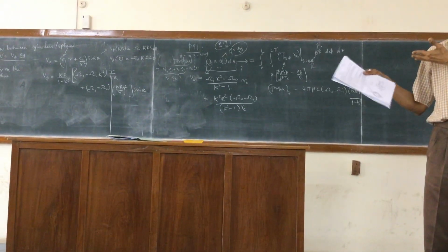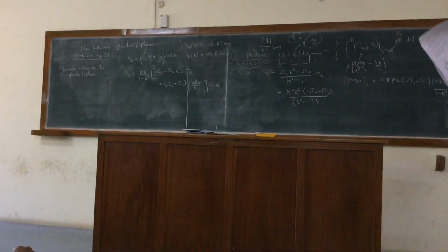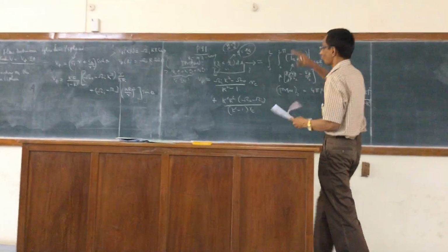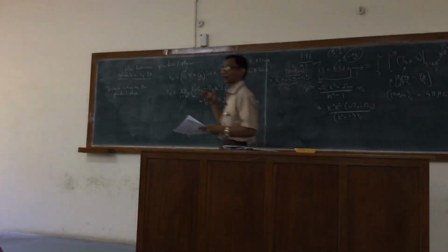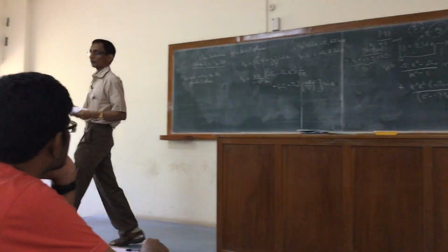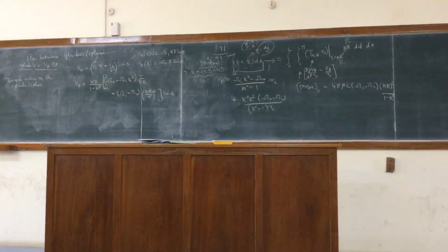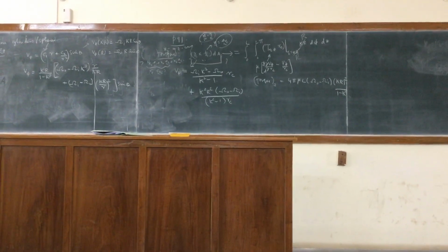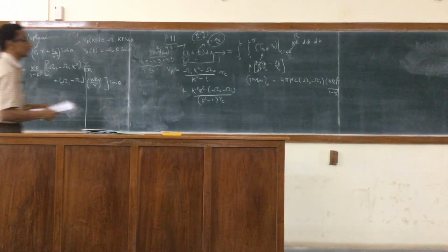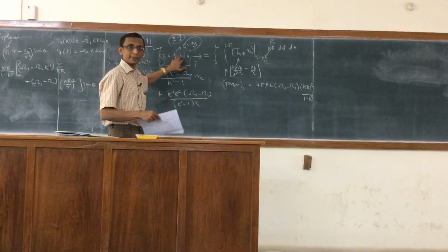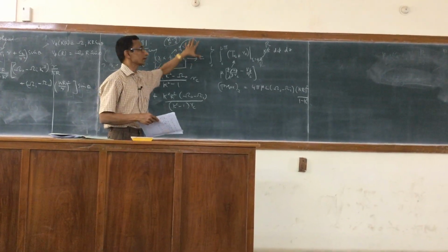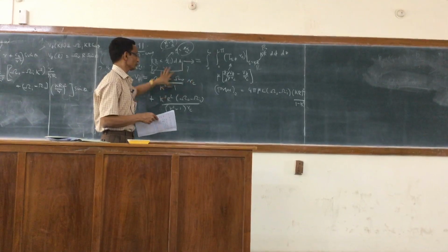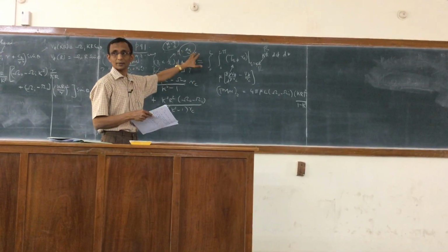Because those are units which are varying with the position, whenever we talk about the overall force or torque, we don't express it in terms of the cylindrical coordinates. It has to be expressed in terms of the Cartesian coordinates alone, which are fixed in space. Right? We have to convert the er, e phi to ex, ey, or e1, e2, and finally substitute. If you stop there, you get the general result.